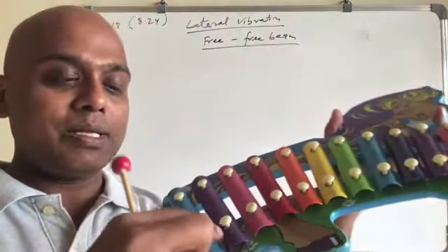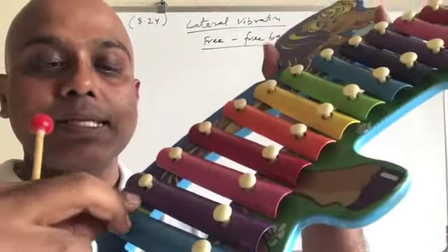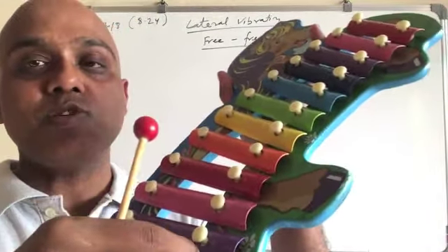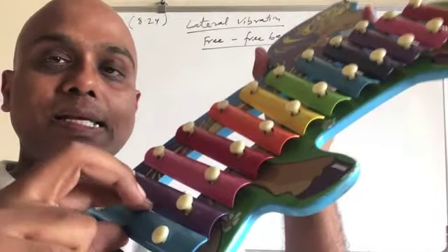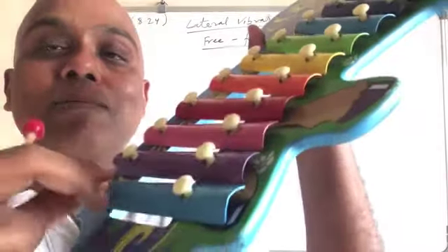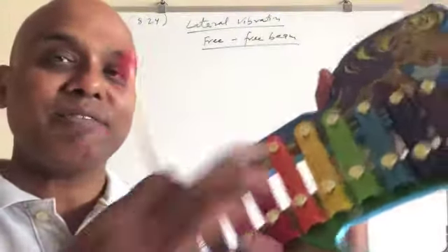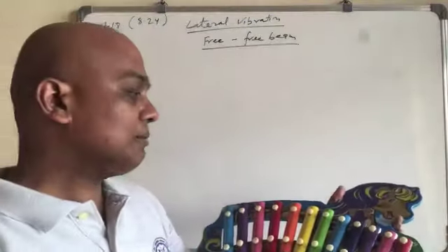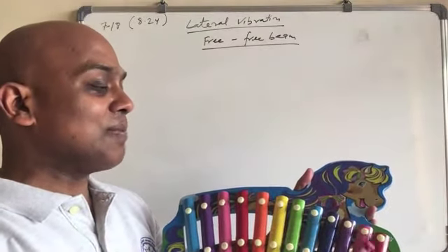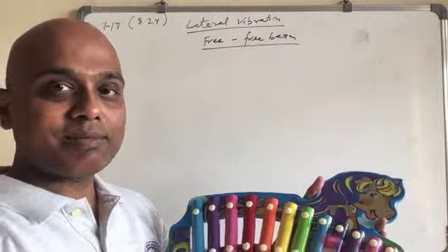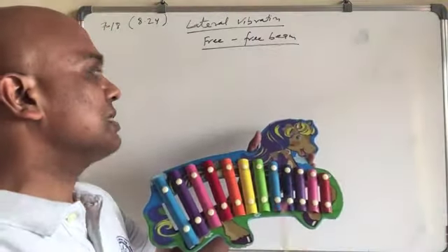The pins are just to keep it in place. However, it is not really clamped here. So that's why it is a free beam, and that's why the length plays an important role in this case. Depending on the length, the frequency will be different.